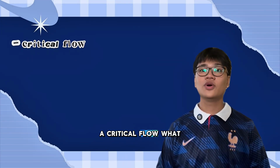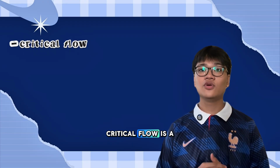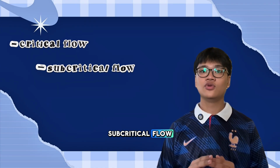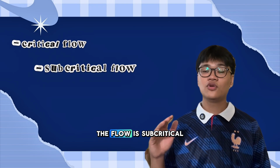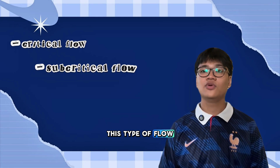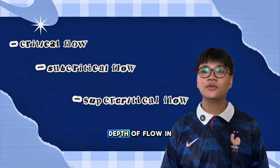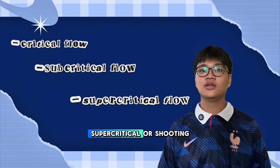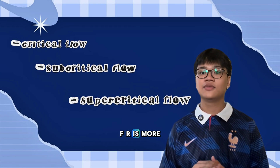Critical flow. What is a critical flow? A critical flow is one with the minimum specific energy. Critical flow is a flow that corresponds to critical depth. Subcritical flow. When the depth of flow in a channel exceeds the critical depth, the flow is subcritical or streaming or calm. The Froude number in this type of flow is Fr less than 1. Supercritical flow. When the depth of flow in a channel is smaller than the critical depth, the flow is supercritical or shooting. The Froude number for this type is Fr more than 1.